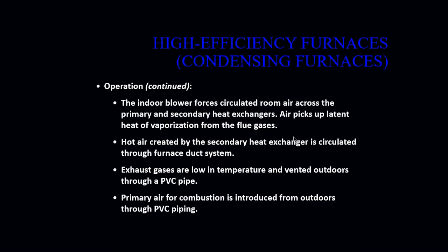The indoor blower is going to force the circulated room air across the primary and secondary heat exchanger. The air picks up that latent heat of vaporization from the flue gases, and the hot air created by the secondary heat exchanger is then circulated through the furnace duct system. Your exhaust gases are low in temperature and vented outdoors through the PVC pipe, and your primary air for combustion is introduced from the outdoors through PVC piping.